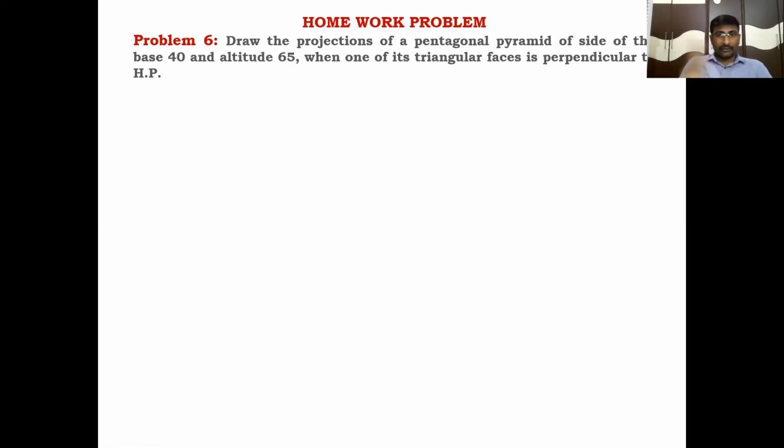So one of the base edges is on the right side. Start the pentagon with the right side as one of the base edges. And one of the triangular faces is perpendicular to HP, which means the axis is inclined to HP. Whenever the triangular face is perpendicular, the axis makes an angle with HP. So angle HP to inclined